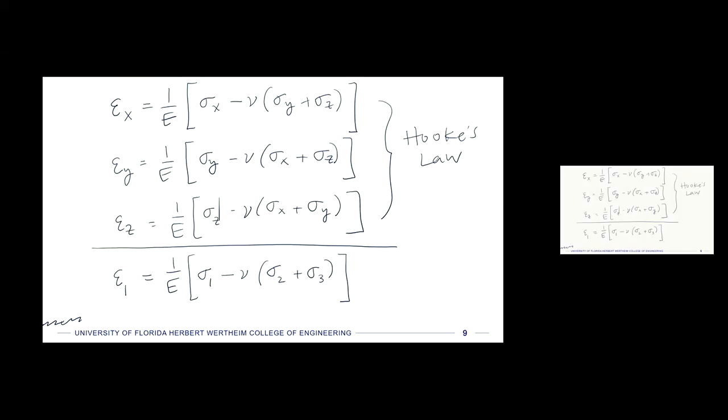And so in this way, we can get not only the principal stresses, right, from solving our matrices and stuff, but now we can get the principal strain. And then we can compare the principal strain to, let's say, a strain to failure, or the strain that exists when the material yields, right? And we can determine, did this material yield or not, right? Based on a complex state of stress rather than just a 1D tensile test. And we can do the same thing for the second principal strain and the third principal strain. It's not as helpful, but we can say that.